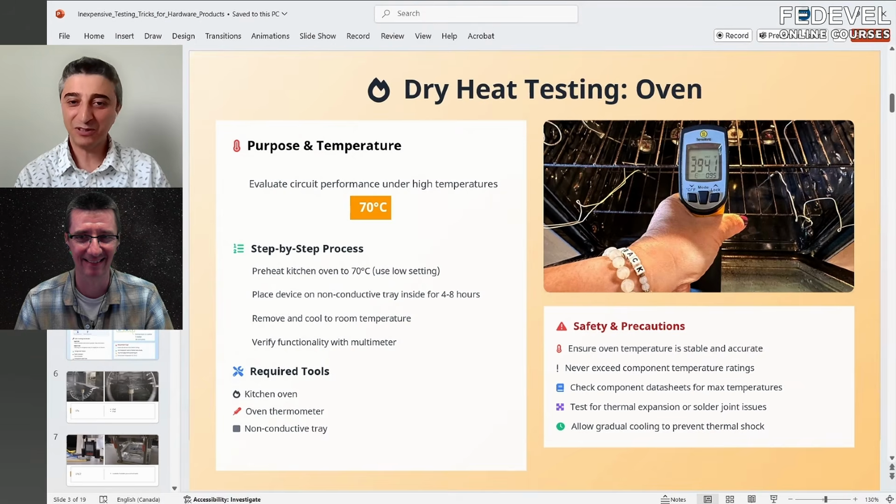So you have to make sure that this is working. How can you find it? Just make sure that the latching relay is really designed for that extreme operating condition. And as you said, I live now in a Canadian city where we go to the extreme end, -40, -35 degrees Celsius. So things might not heat up, but if you're using your vehicle during the summer, you might reach 50, 60 degrees Celsius and maybe even beyond that. So high temperature is really one of the critical paths for the design to be reliable.